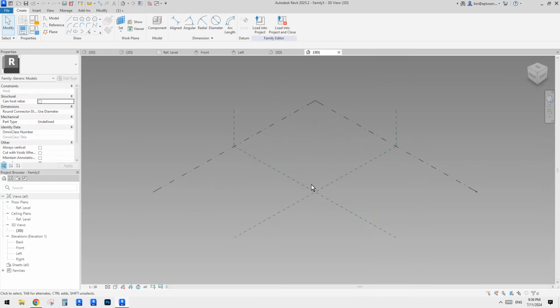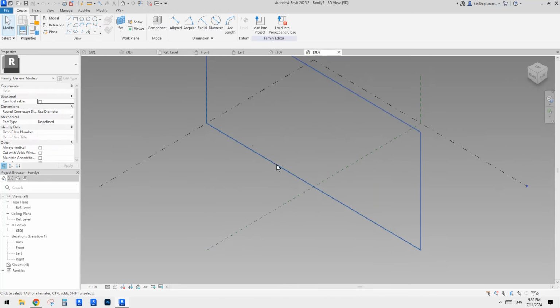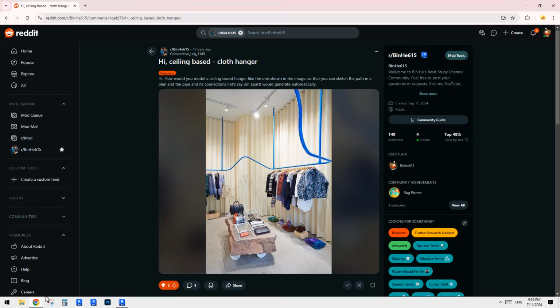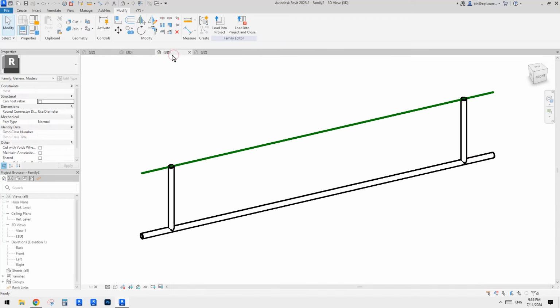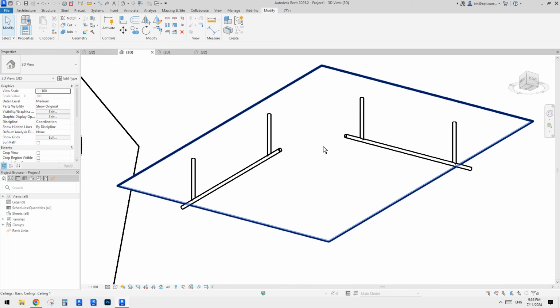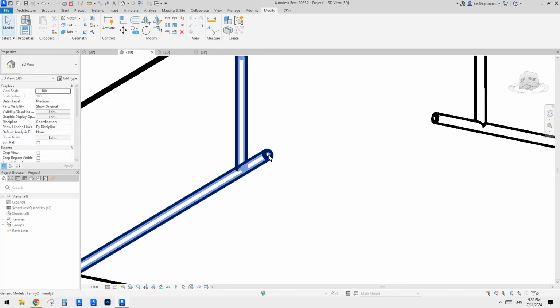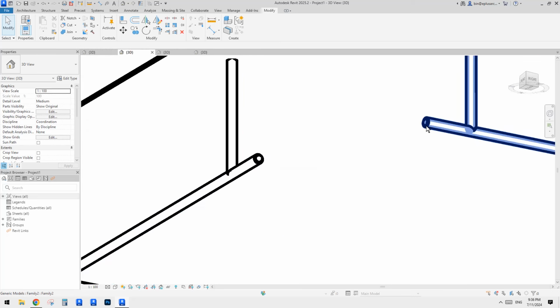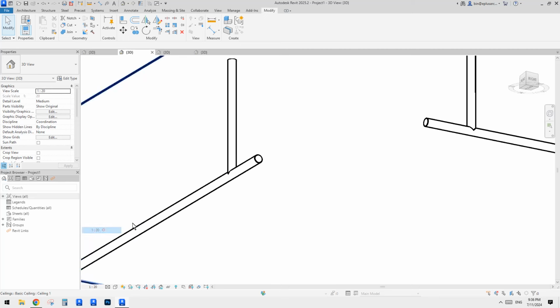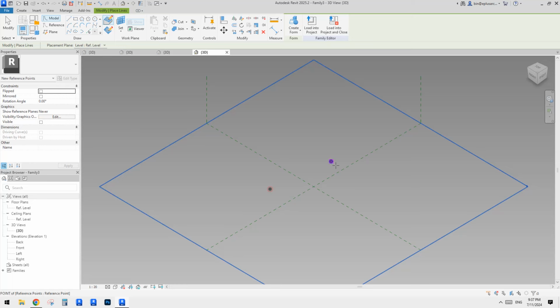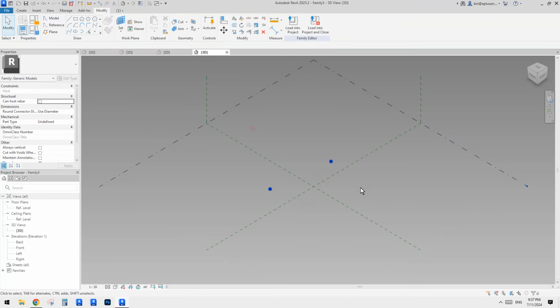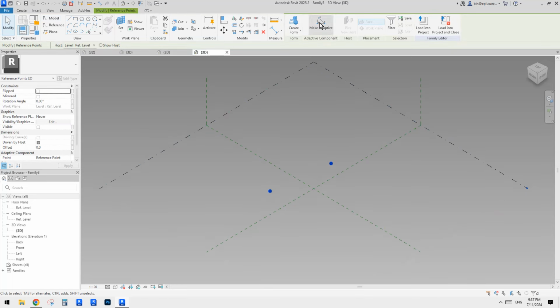It's actually quite simple. I'll show you. We will need 2 adaptive points. Oh, sorry, wrong one. Hang on. Where's my project? Here, not here. This one. We will place onto here the center point of this one and the center point of this one. Let me change the scale. Yeah, that's better. Place anywhere, place 2 points. Select done, make adaptive.